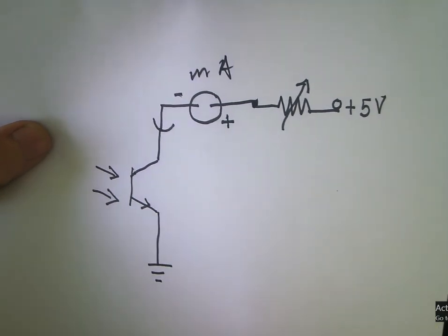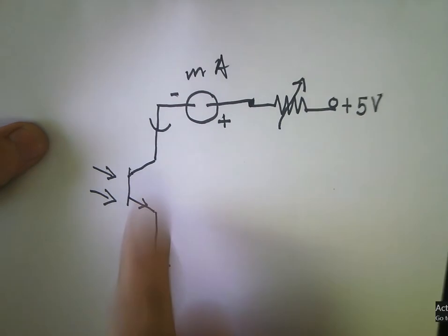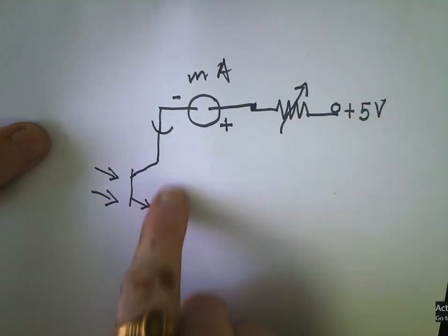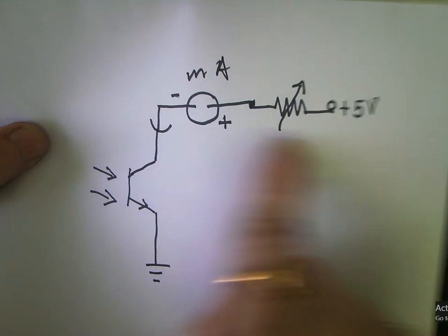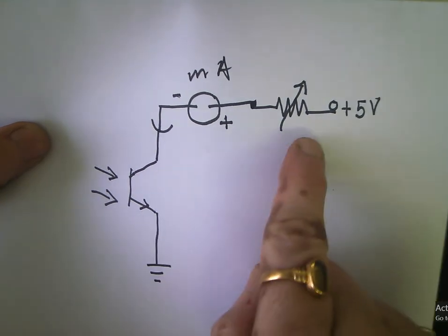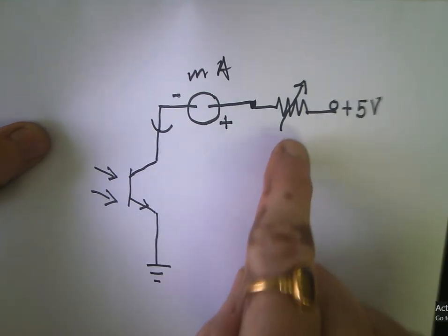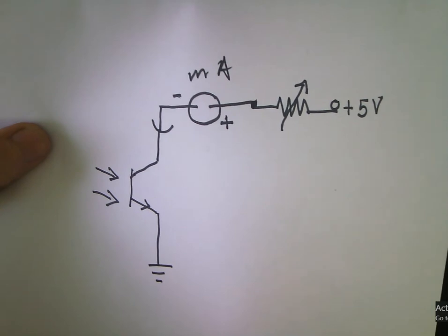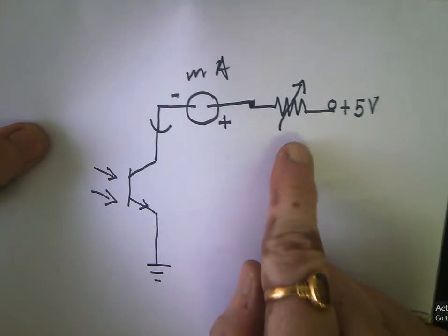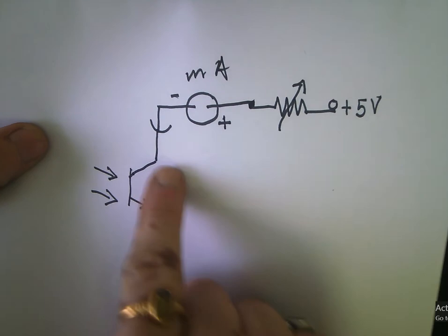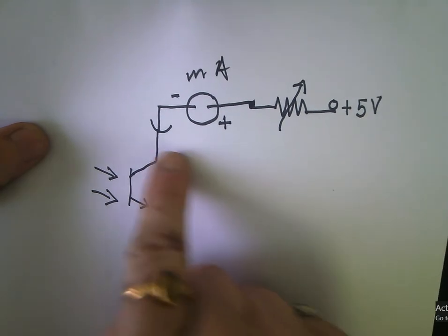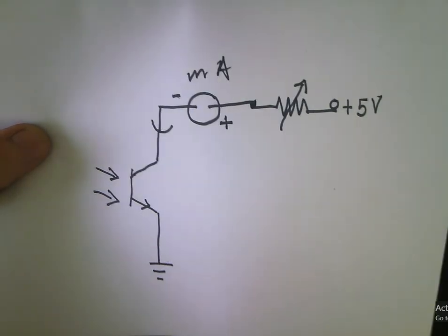Now, why it will happen like that? Because now the transistor has started conducting current, and therefore there is a collector current. Since there is a collector current, there will be a voltage drop across this collector resistance. Now, when there will be voltage drop, you can very easily find that KVL shows that there will be a decrease in the value of VCE.